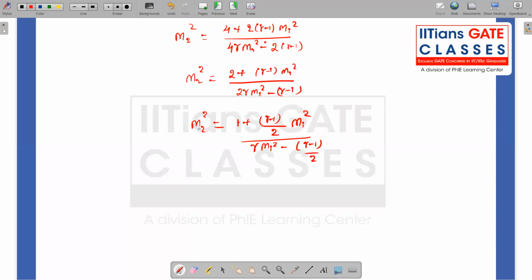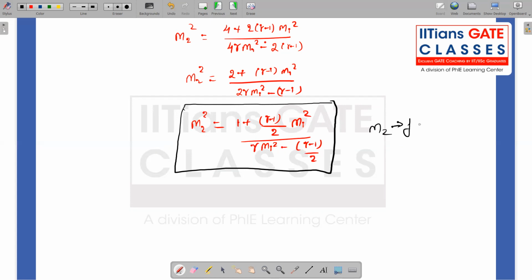It is important to remember this is relating m2 square to m1 square, not m2 in terms of m1 square. If you want to calculate m2, which is usually the case, then you have to take the square root of this equation. So this is the relation that relates the upstream Mach number to the downstream Mach number. Now see, m2 is a function of m1 only, given that the gas is calorically perfect and gamma is constant, so we are treating it as constant. But here you can see m2 is a function of m1 only.